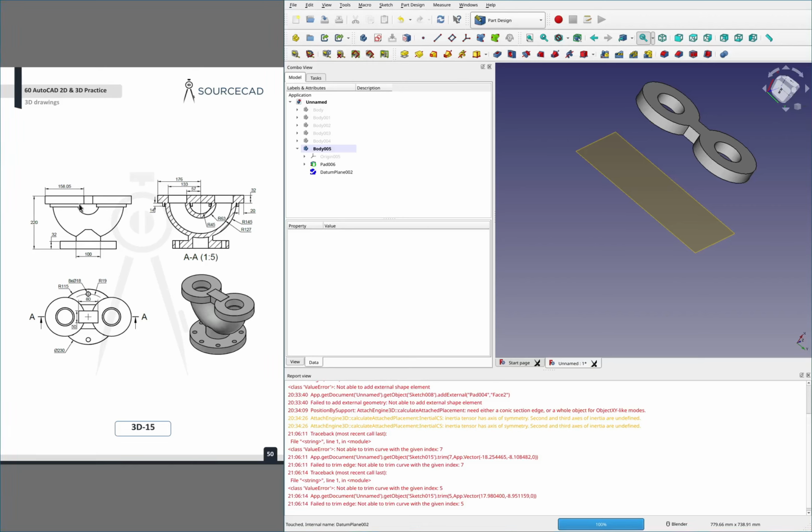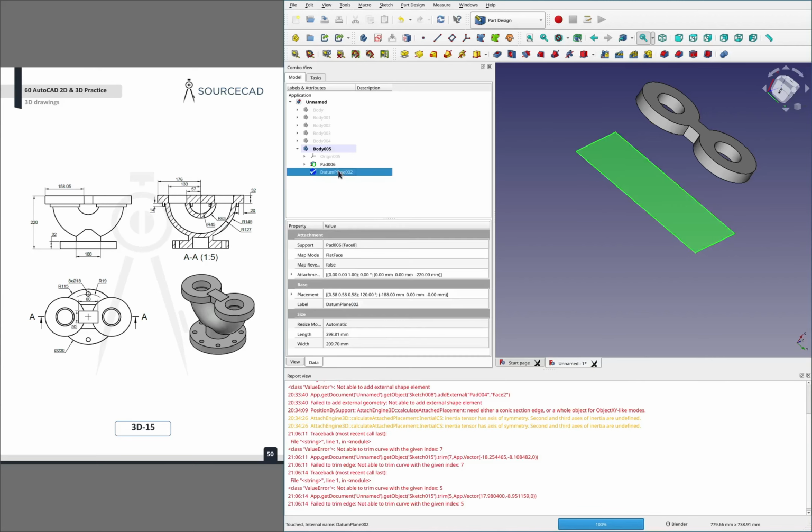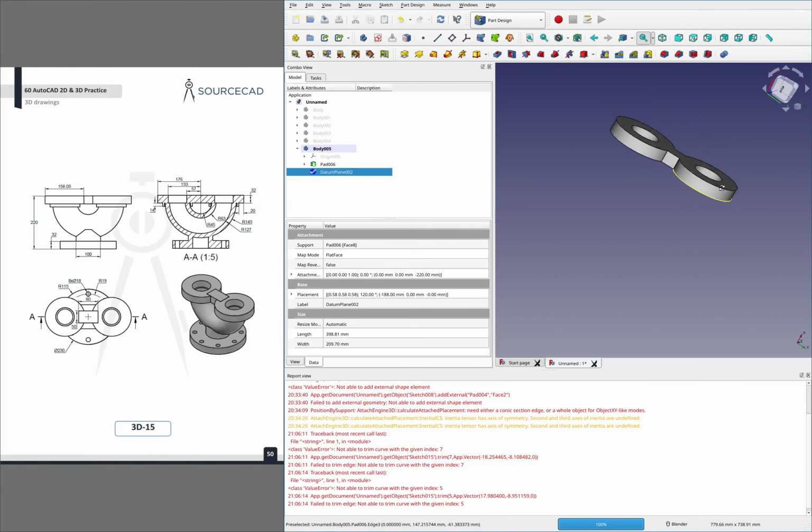Maybe we try this up to surface thing and we'll see if it works, and if it doesn't, then we'll do some funky stuff with two bodies and Boolean combining and subtracting from one another in order to make this. Turns out to be a pretty interesting part. So I'm going to go ahead and hide this plane since I decided not to use it.